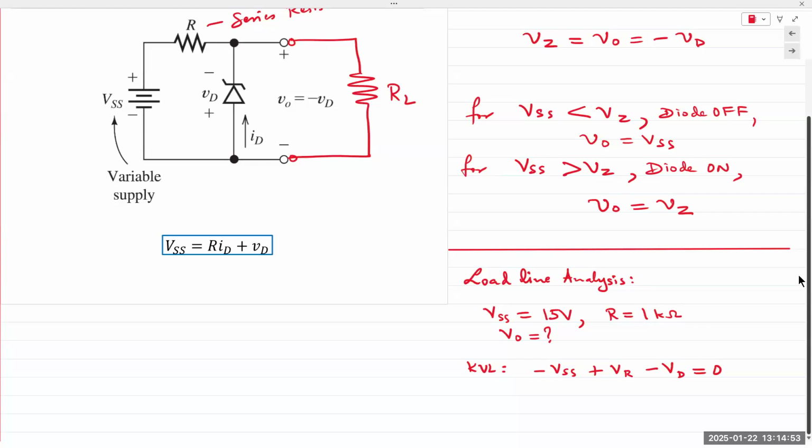But Zener diode is connected in reverse bias. So remember last class I stated, even though we say VZ is positive, if you are referring to diode voltage and diode current, anode is positive, cathode is negative. So VD would be negative, ID would be negative. And it's represented in the graph in the third quadrant in reverse bias because it is reverse bias. You all with me so far? And that's why I have the sign as minus VD and not plus. Okay, so keep that in mind.